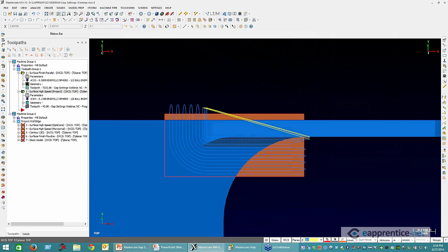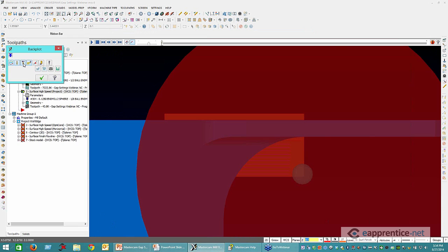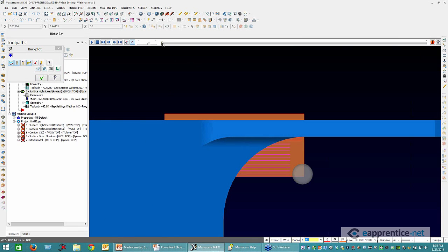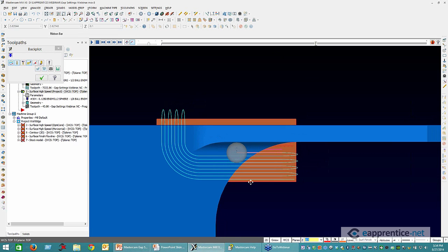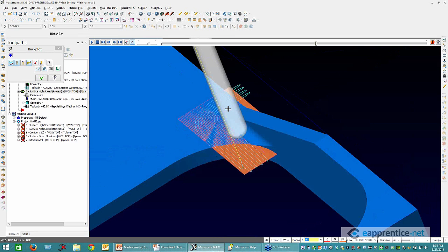So one of the things that I probably should have done, all of these contours right now are centerline contours. What I should have done was offset the first contour by the radius of my tool. Because what's happening is as we get, let me turn off the holder here. As we continue this motion, this all looks good, but you can see that I'm getting close to the tangent point. There's where we're basically tangent, and we're actually machining that correctly.